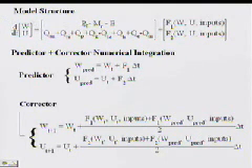In this equation, we do not distinguish whether precipitation is rain or snow, because we say all the water gets added to the snowpack. If it's in the liquid phase, it will bring energy with it that might cause more water to melt, and it'll end up adding to the liquid water content of the snow, which if that gets large enough will drain out of the bottom. So rain gets added and then perhaps drains out or perhaps refreezes depending on the energy state of the snow.